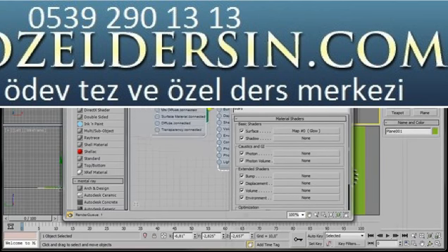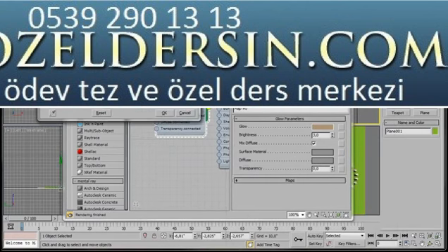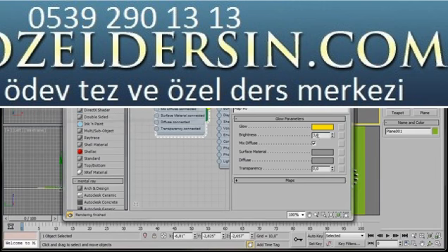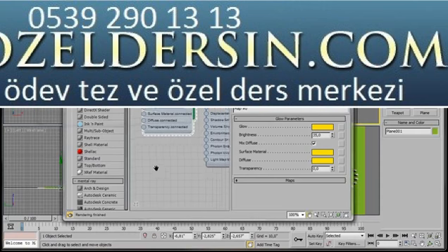Okay, let's double click up now on the glow shader. We'll go to the diffuse color slot, and here in the color selector we're going to select the yellow, a nice bright yellow, and say OK. That's going to be our glow. Our brightness we can change to 35. Let's go to our surface material. We'll select the eyedropper and select the color from our glow, and we'll do the same again for our diffuse color. There we are, we'll say OK.